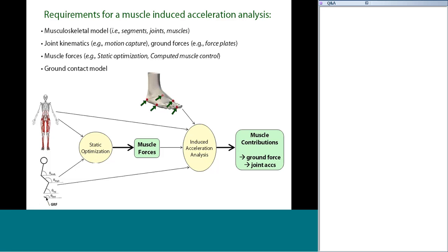But if you have, for example, a very bad contact model, let's say you're trying to use a pure weld joint throughout the whole stance phase of walking, that's not really representative of how we walk. The weld joint does not allow any rotation or translation of the foot. So this restriction will cause superposition errors to occur because we actually have rotations and translations of the foot during our experiment. So superposition error can basically be seen as a level of inconsistency between your foot contact model and your experimental foot kinematics.